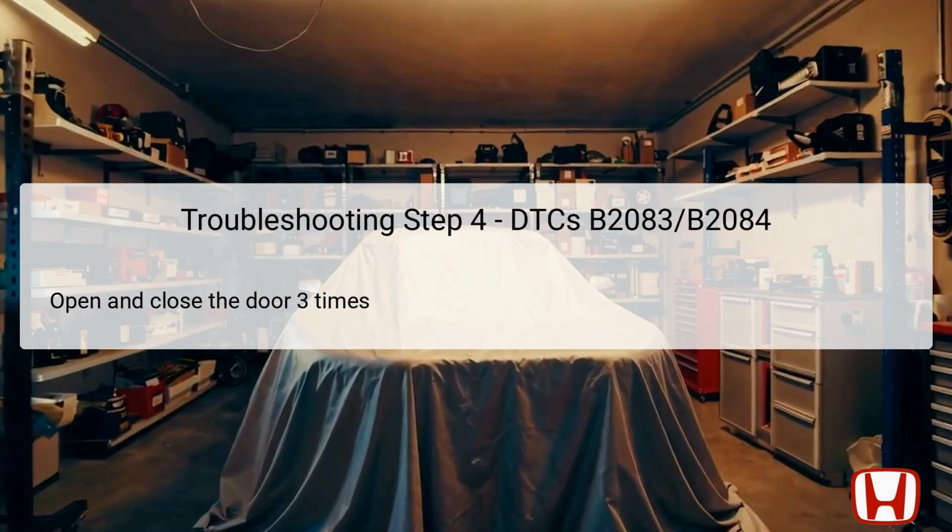Next, technicians should open and close the right power sliding door at least 3 times. This repetitive action allows for thorough testing of the door's operation, while simultaneously giving the control unit the opportunity to adapt and learn from the activity. During this procedure, it's important to observe if the door operates smoothly without stalling or failing to open or close completely. This step helps to determine if the previous DTCs are still present and functioning correctly.